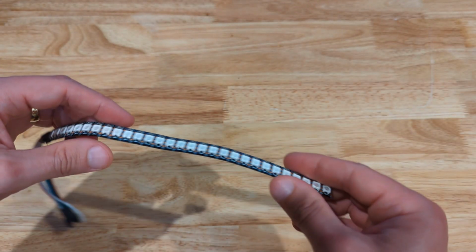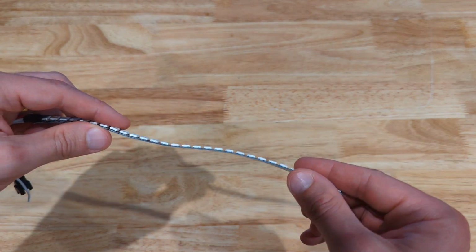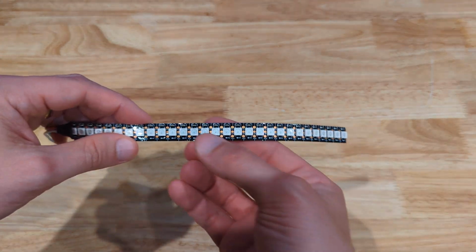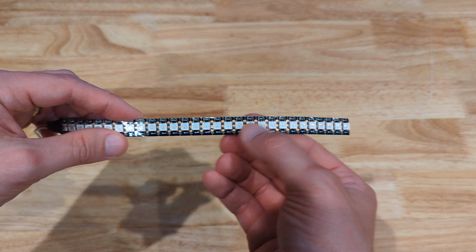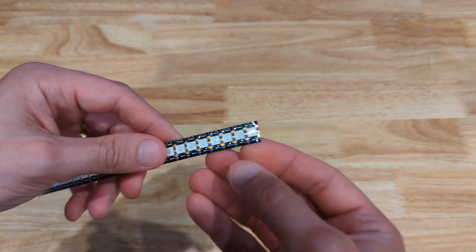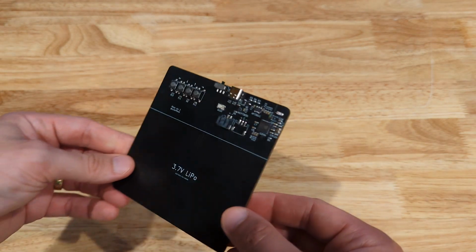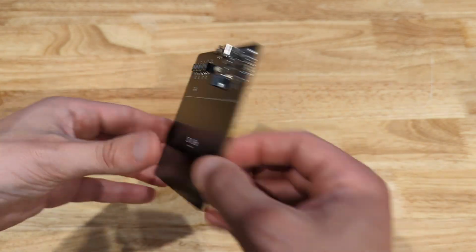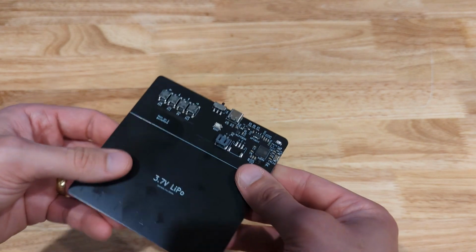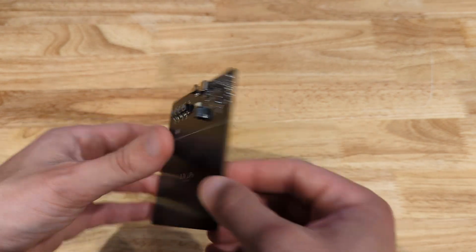One thing about LEDs is that I'm using these strips, and that is much nicer because I don't need to solder on each individual LED. Instead, I can buy these meter-long strips, cut them to length, and just need to attach them at the very end to the PCB. What's nice about it is that it makes the PCB single-sided. I only need to populate parts on one side and can then reflow it.